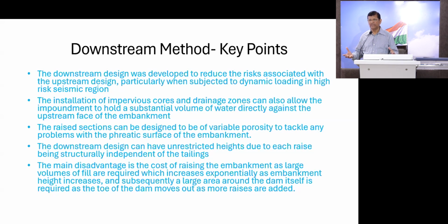You need huge quantities of material from outside the mines, and it is also highly expensive compared to the upstream dam. So though this is a stable structure, it is very expensive. Economy is also important for mining, so they have to weigh whether it is economically viable or not, because if it is not, they will not go that way and will take the risk with upstream.